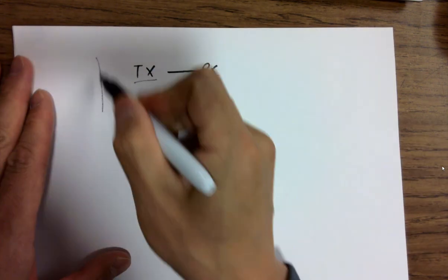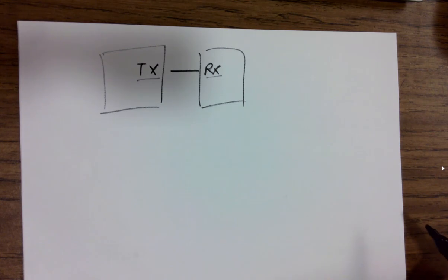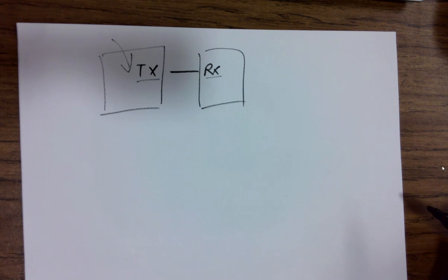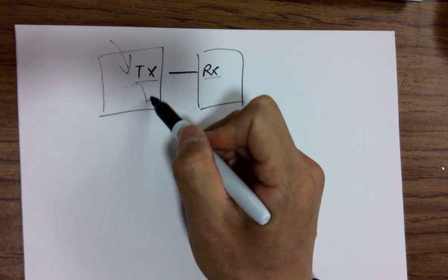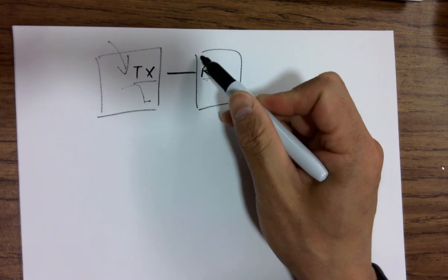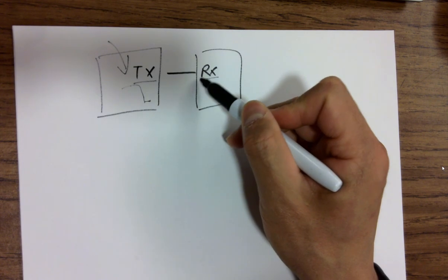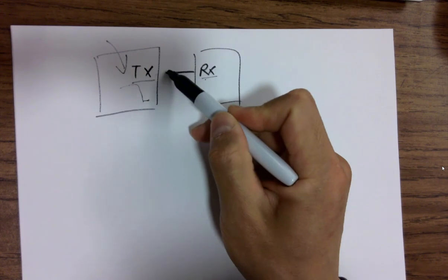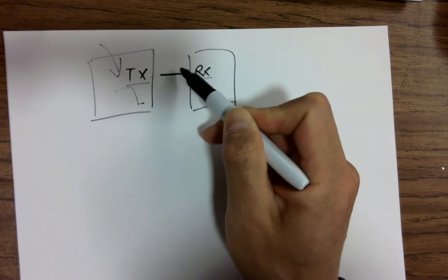So the difference is when the digital designer, whoever works for Microchip and designing all these Arduino chips, right? So they wrote all the Verilog, the hardware description language, to design the TX and RX modules, right? So they have to make sure that TX does that pulling down activity, and RX is just using a state machine to detect it instead of pulling it down by itself. So that's the only difference. But it's just one wire. If this pulls down, this one will sense that 0 volts as well at the same time. It's just one node, just one voltage, right?